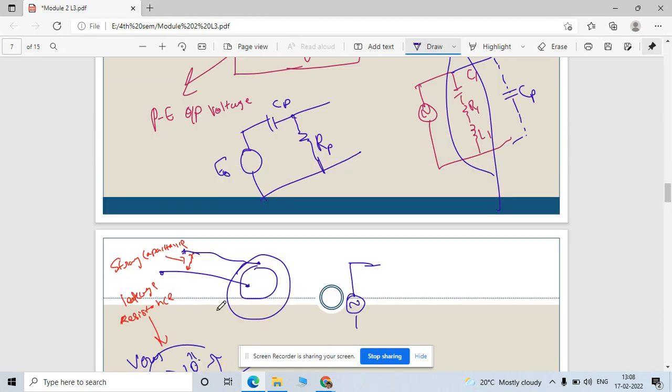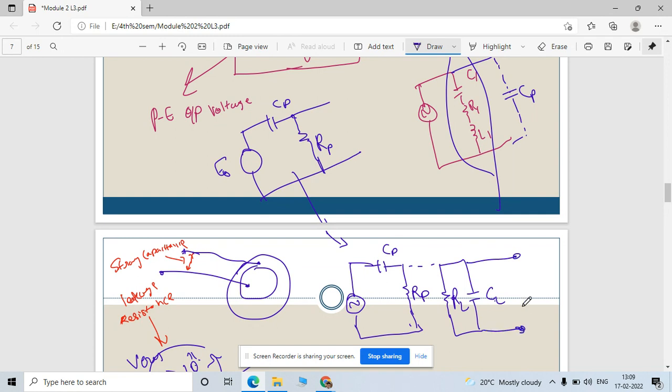एक्चुअली जब आप ये कनेक्शन करते हो ना, तब आपका ये जो सर्किट है, this circuit will be modified and your circuit will look just like that. This is your RL, meaning leakage resistance, and this is your capacitance. Okay, so this is your load, this wire capacitance, or you can say leakage capacitance, and this is your output voltage at the load side.